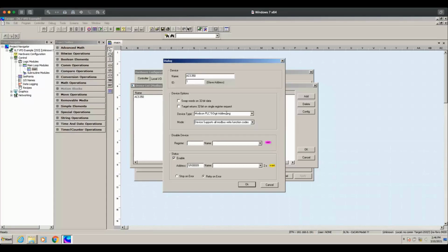And then this is where we get down to what we were talking about earlier, the style of Modbus address that's in the user's manual for the product. Now, Modbus 5-digit addressing is by far the most common. 6-digit addressing is more common for Modbus over Ethernet, but I guess there's some devices that support it as well. And then if you scroll down a little further, you'll see we've also got some of those generic decimal address and hexadecimal address options that you might find in the back of your user's manual for your drive. That being said, if you're not sure, stick with Modbus or Modicon 5-digit addressing scheme. That's by far the most common.